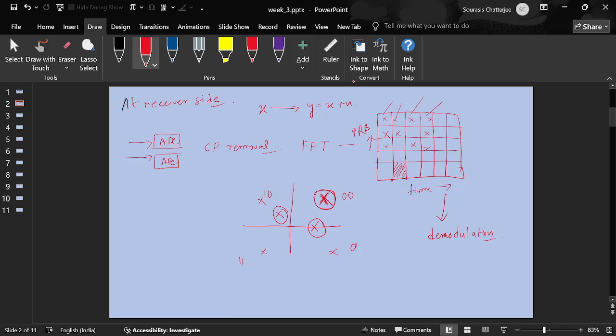So there are actually a lot of different kinds of noise at the receiver end. Let's speak about the first, thermal noise. It's caused by the movement of electrons. Electrons don't move at the ideal temperature of minus 273 degrees centigrade, but that doesn't usually happen, right? We usually have some non-zero temperature, so electrons keep on moving and these movements are independent and that leads to noise. So whatever we see as n here is actually a summation of many different noises, n1, n2, n3. Those all sum up and we are calling it n.